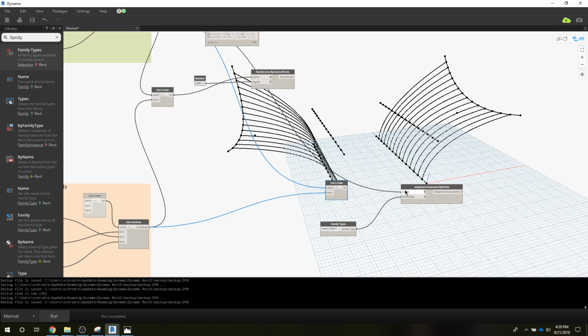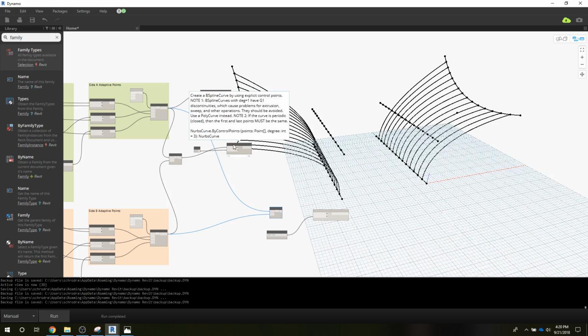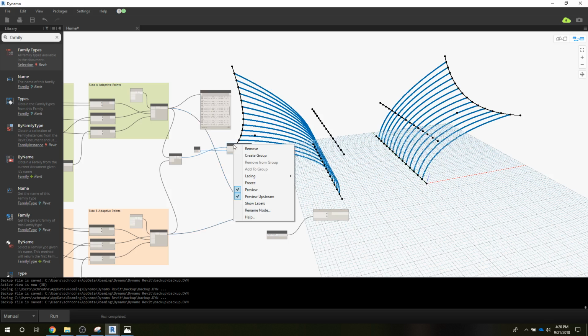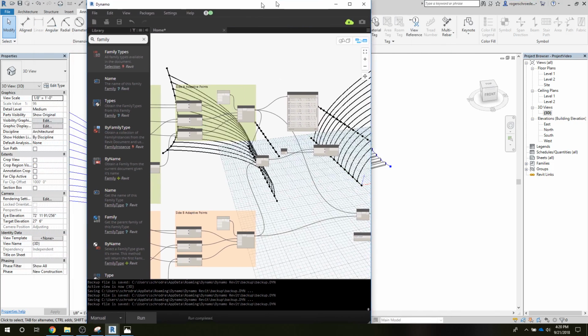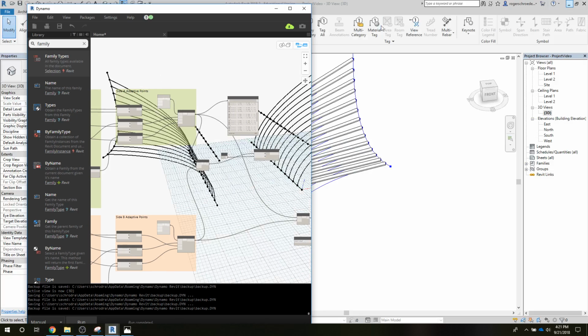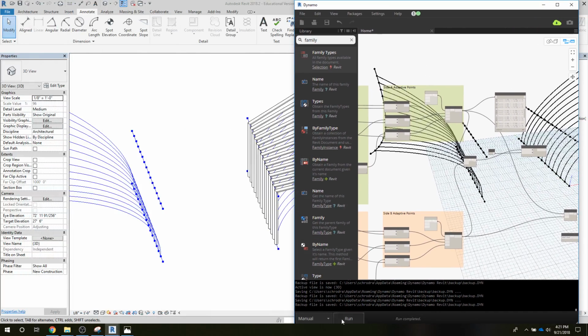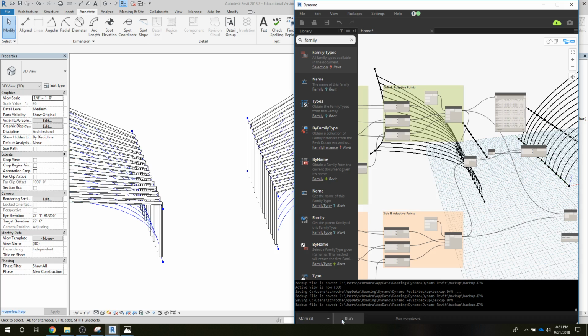And so in the list create, the first one is the points from the one list, and we have the list from the other one. And we can actually get rid of this now. So I'll just go ahead and delete this. Well, I'll leave it here because it gives us some visualization on the Dynamo side. And let's plug this into here. I'll shrink this down. Oops, it grew back up again. And let's hit run. And we should go ahead and get the other ones on the other side.